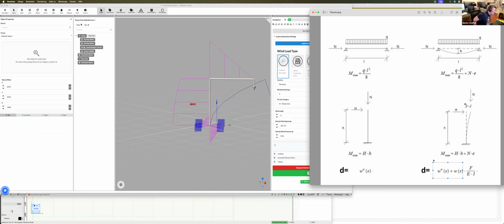So typically the question now is, what does this do for me? The reason we've added this is that we have a lot of functionality where buckling is a problem. Buckling is a stability problem which can be captured by the second order calculation.